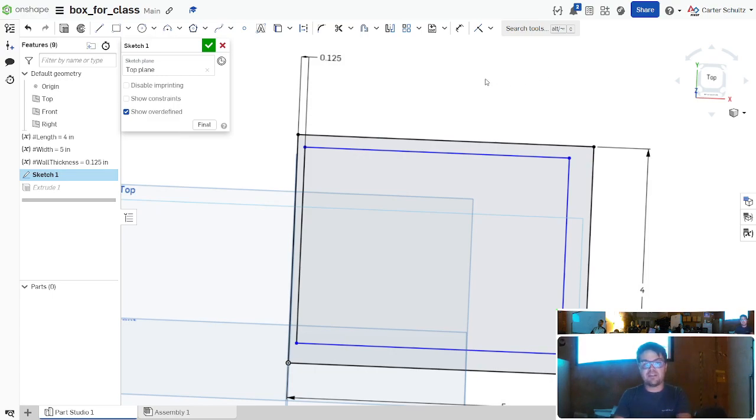And the first thing I'm going to do is create a line. So I hit L, this is the line tool here, I'm just going to draw a line, and I'm going to slide my cursor along this line until the symbol for the constraint changes. And you see how it's showing me coincident, coincident, coincident, and then it changes to that symbol? That symbol is the midpoint symbol, and so this line is going to end up constrained to the midpoint of that, and I can go over here and it'll snap to the midpoint again. So now I have a line that is already black because it's already tied to the midpoints on both of these guys.